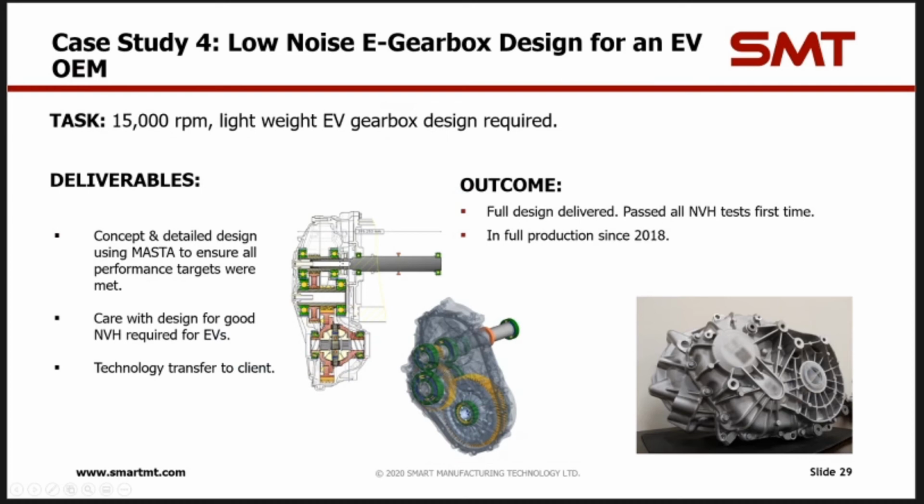This project is a design of an EV gearbox. It's been a very successful EV gearbox. One of the main challenges with this was the high installation angle that made getting oil to all the gears challenging. The end result was very high power density and exceptional NVH performance, meeting the NVH targets first time.